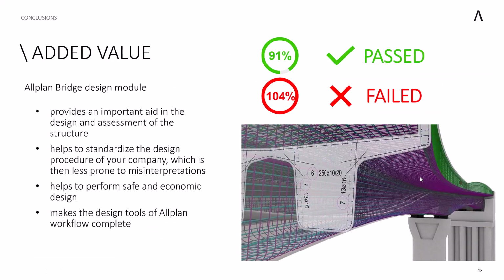Ladies and gentlemen, I hope that I showed you how to perform the design of pre-stressed girder in Allplan Bridge. The correct design is based primarily on the correct pre-stressing level. Only certain partial issues can be fine-tuned with reinforcement. Aging, construction stages and rheological phenomena also play an important role. It is therefore necessary to understand the principles of structure mechanics and the methods prescribed by standards.